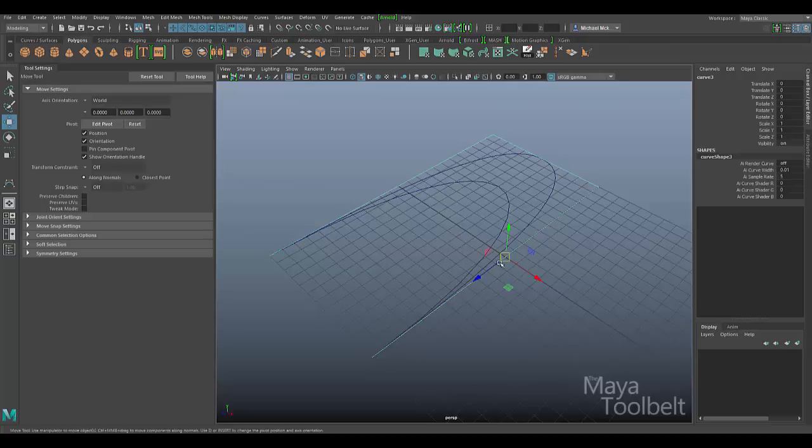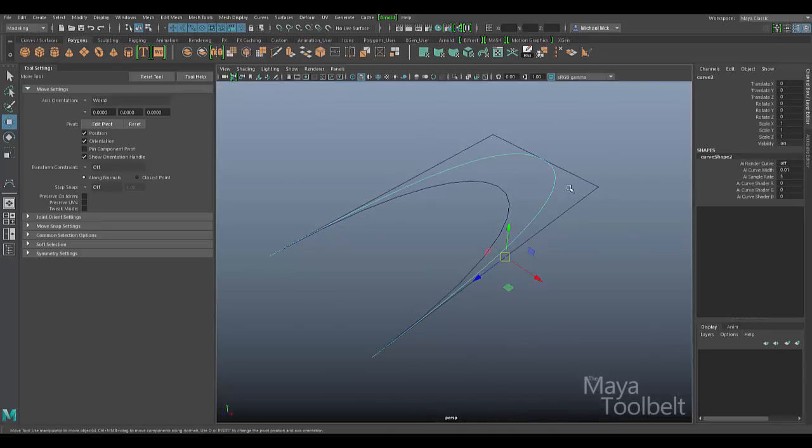And then I hit enter. And you can see that curve does not have any curvature to it. It's simply straight lines between points. Let me hide the grid for now. So this is a linear curve. This is the curve degree of 2. This is a cubic, or curve degree of 3, curve.